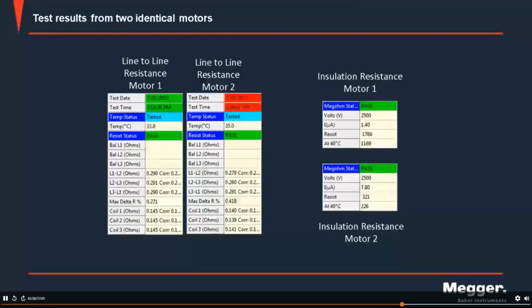And in this case, it was the first time we were testing, so we didn't have any trendable comparisons, no time trends. But because they're exactly the same design, we were able to make what I call a comparison of like design. So we're trending by comparison in this case, and looking for deviations. And here's a spoiler alert: we got something that's red, but it's not resistance. There's a slight difference in resistance here, but it's not significant.